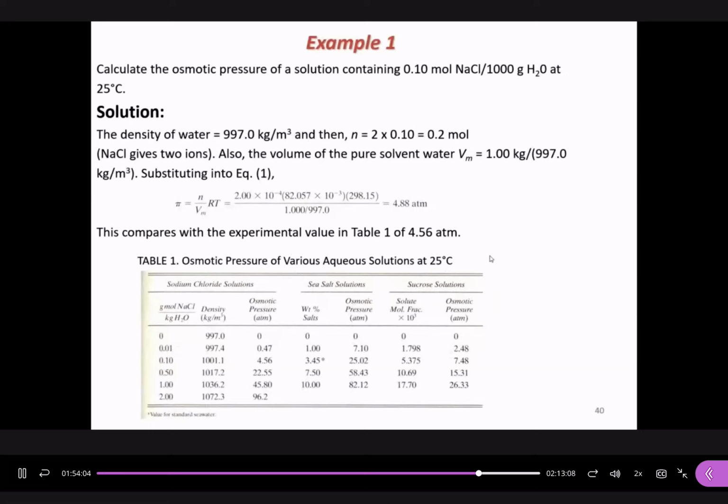In reality, the measurement is 25 atmosphere. So that is a threshold pressure. If you apply a pressure lower than 25, you will not get water. You have to overcome that pressure barrier. So in reality, what's the pressure we use at TKO desalination plant? Anyone knows? It's around 60, right? So almost double the pressure.